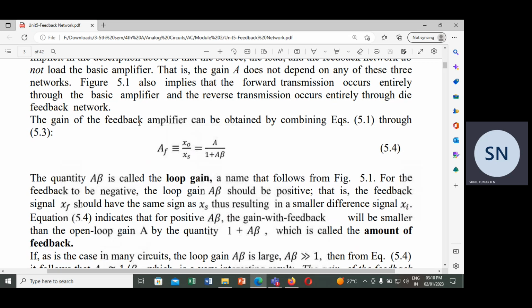But when you see this in the closed loop form, whether it is a voltage follower or a non-inverting or inverting, the gain is going to be controlled by the external feedback components. So these feedback components are going to reduce the gain of the op-amp. The same way, negative feedback has reduced the open loop amplifier gain by a factor of 1 plus A into beta. So normally, A into beta will usually be greater than 1.